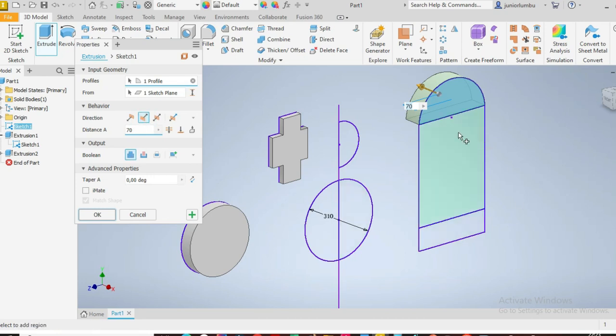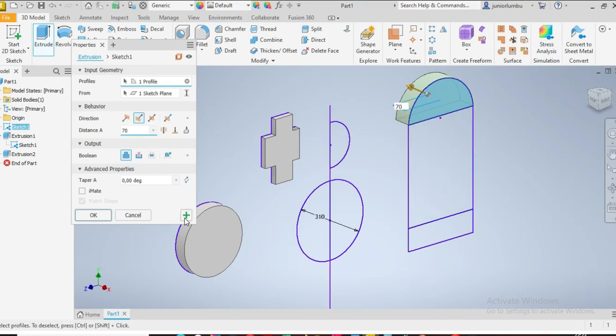So now this one here, I want to add 100 millimeters. Then I come here, I say plus. Now I want to add 100 millimeters on this one. So come here, I'll say 100 millimeters. So now I'll click here, then I'll say, how do I want to add the 100 millimeters? Now I'll say, no, both sides of my drawing plane.